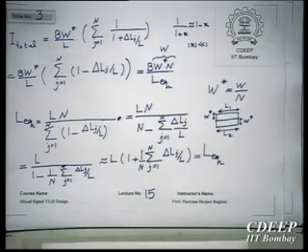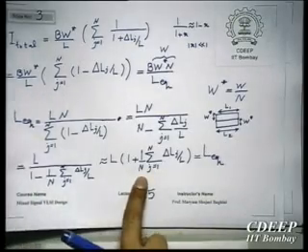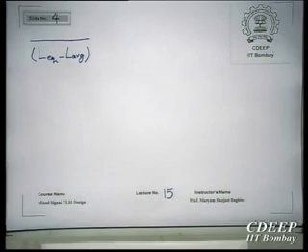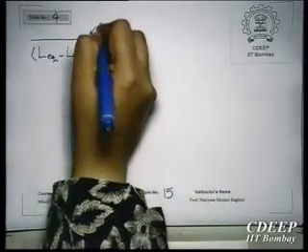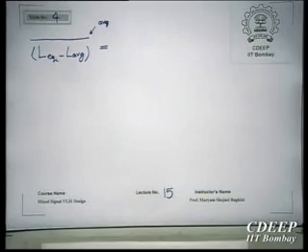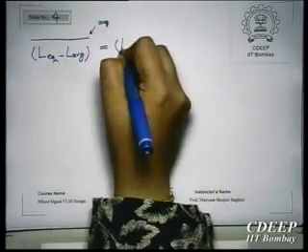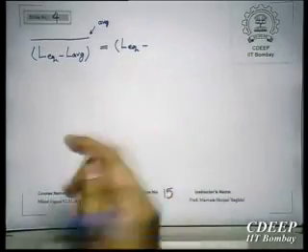It means that if you have two transistors and you choose a long L for both of them for a given W which doesn't have any variation, you will get better matching. In other words, each one of them will have an L equivalent to L. Therefore, the two L's are the same, meaning none of them will observe variation because L is large. We are sampling with a large number of samples N. So we just calculate this standard deviation. This bar means average. Don't confuse it with a fraction. So then this will be L equivalent. So L average of course is L.